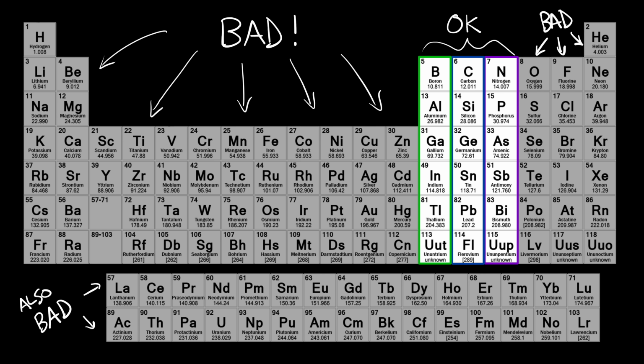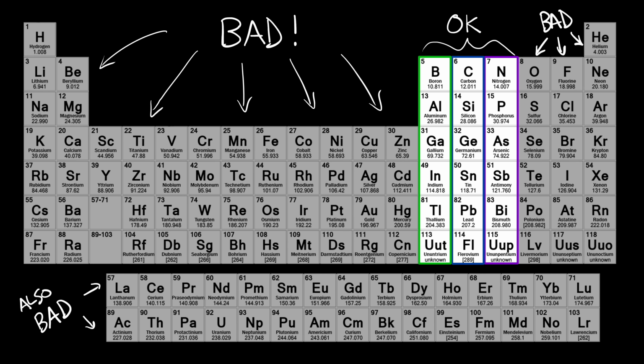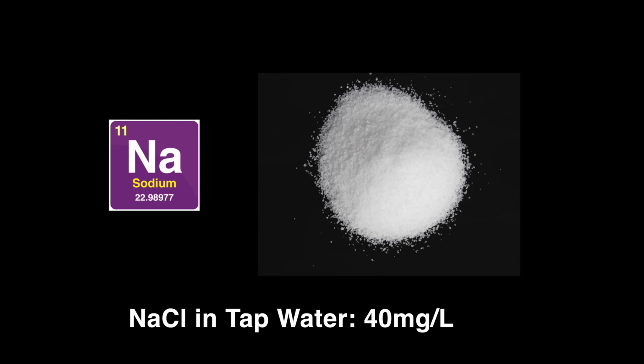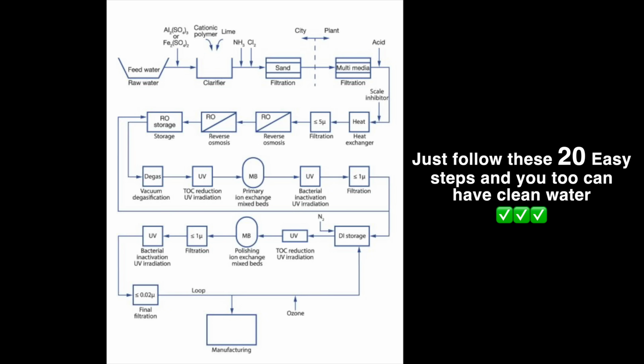Now, fortunately, most of these atoms are not all that common. You don't really need to be paranoid about uranium contamination, for example, unless your semiconductor fab happens to be located near the exposed core of a nuclear reactor, in which case you probably have bigger problems to deal with. However, some contaminants are extremely common, and care must be taken to avoid them. Sodium, for example, is so plentiful and so detrimental that semiconductor fabs spend millions of dollars to remove sodium impurities from their dopants and even their water.